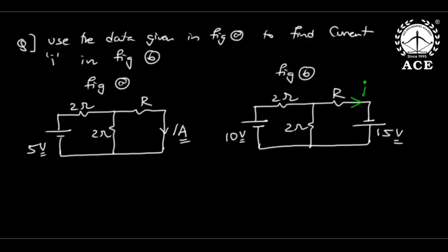Okay, everybody, see here, in this problem there are two sources, sir. You cannot directly apply reciprocity. We know reciprocity is valid only for a single source network. Then what to do first? First apply the superposition theorem. Chalo. Now here, first I will apply the superposition theorem.